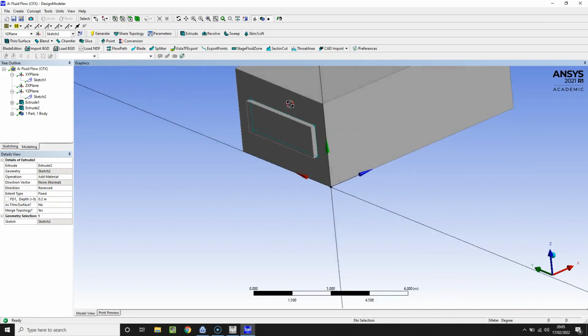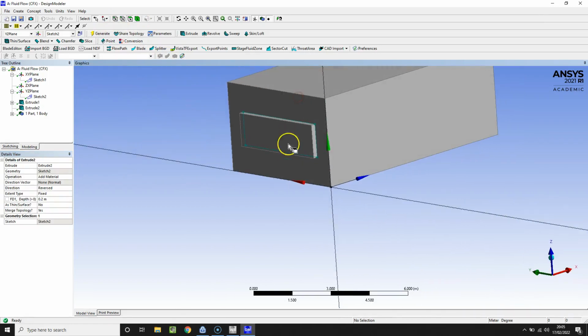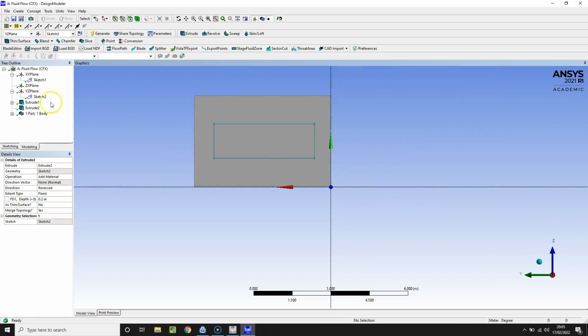And finally, there is a radiator that sits underneath the window inside the room. So we have to do something a little bit different here. You have to create another plane off this ZY plane that sits inside the domain, and then extrude the radiator into that. So just again, viewing this negative x direction, looking at this YZ plane, and creating another plane from it.